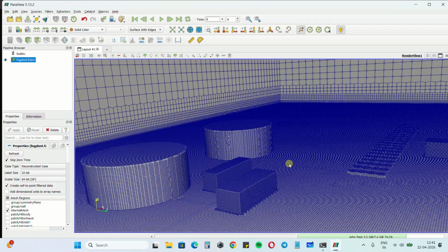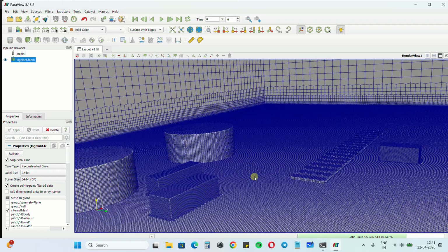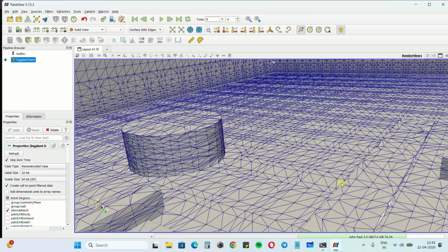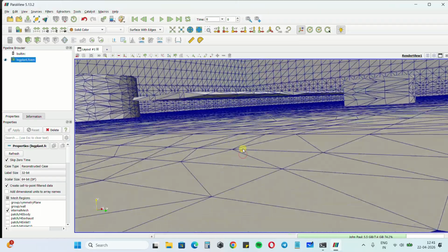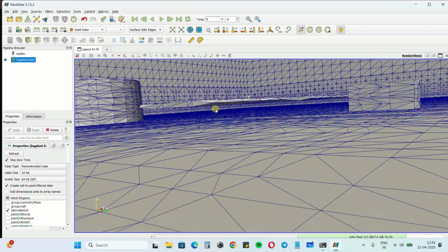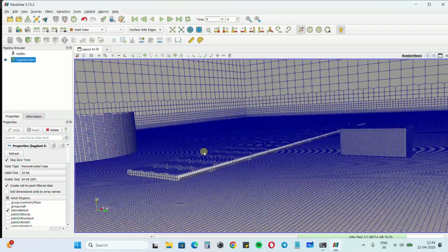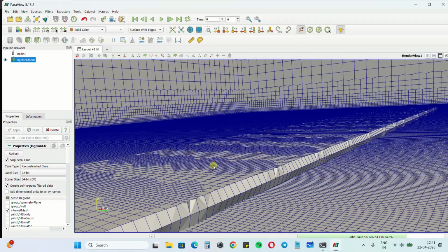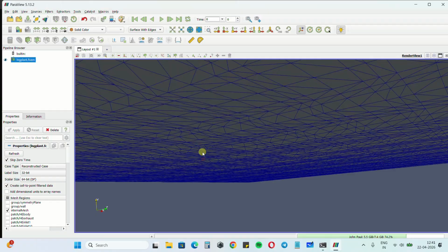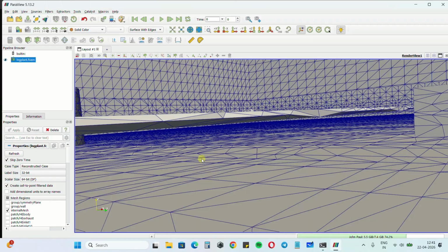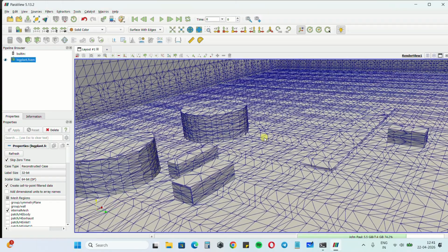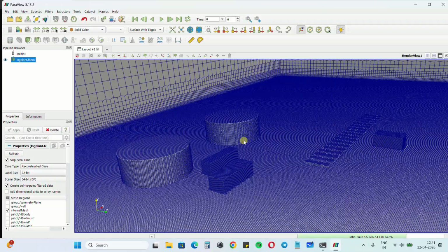You can't actually see the baffle zone geometry because it's just a tool to select the cells for the cell zone. Here you can see the heat exchanger body, which is actually floating in the domain. On the top you have the exhaust faces, and on the bottom you have inlet faces. So the mesh looks fine. Now we can actually start setting up the boundary conditions.